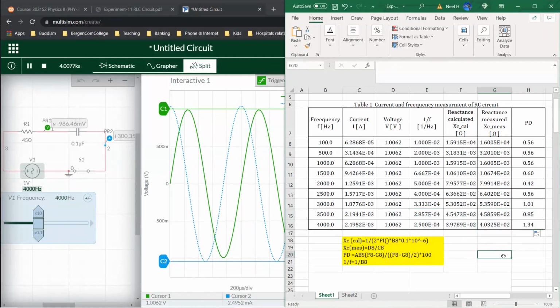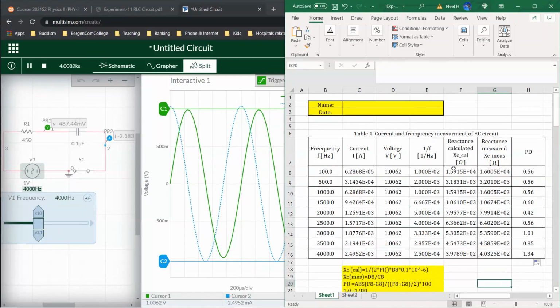Looks good. So if you look at the numbers, the reactance is 1 over 2 pi f times C, right? Since I'm increasing the frequency, it is inverse proportionality. So the reactance effect should be decreasing, right? So that's what we see. It started like 10 to the 4 positive, and then it goes to 10 to the 3, now 10 to the 2, right? The magnitude of that is actually decreasing. So that's inverse proportionality. That's a good indicator.